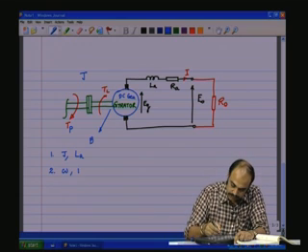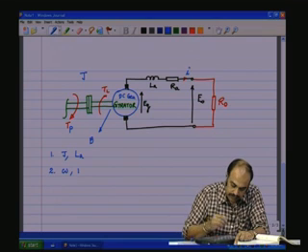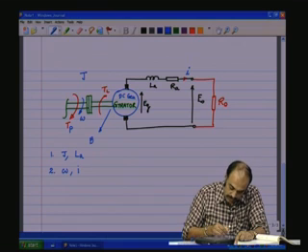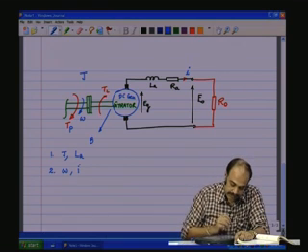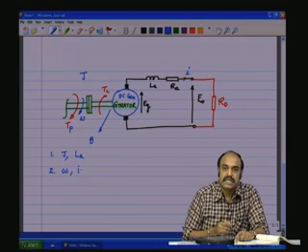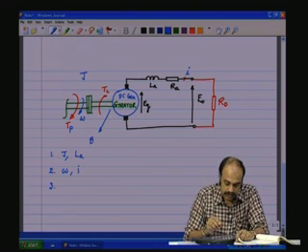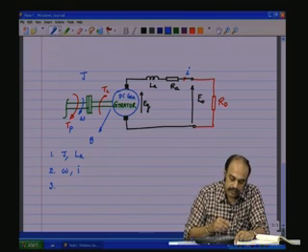Let us represent the load current, instead of a capital I, as a lowercase i. We also have the speed of rotation omega and the load current i on the electrical side. So, omega and i are the state variables. Next, we take one dynamic element after the other and try to construct the dynamic relationship.